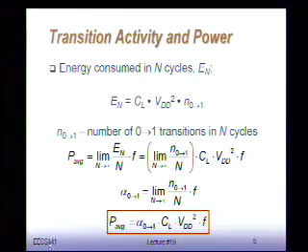Remember the inverter case, this is the power of a particular node in the network. Right? So the energy dissipated at a node in the network, the dynamic power, is equal to the capacitance on that node times VDD squared times the clock frequency or the repetition rate. And then a very important factor, which is this alpha 0 to 1, the probability that for a clock transition, I will have a 0 to 1 transition on that node.